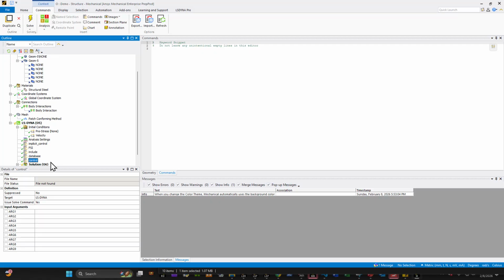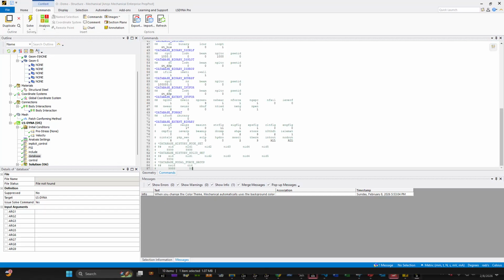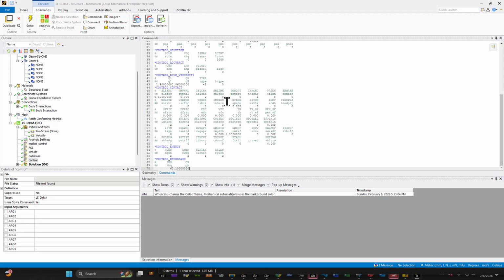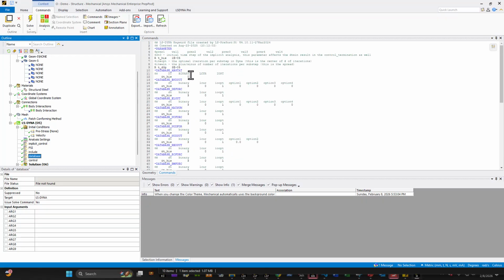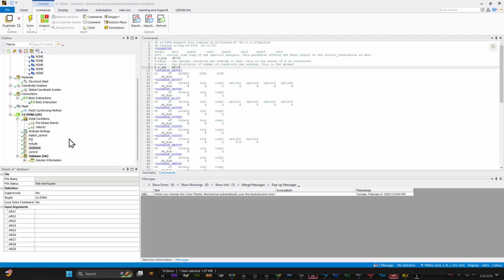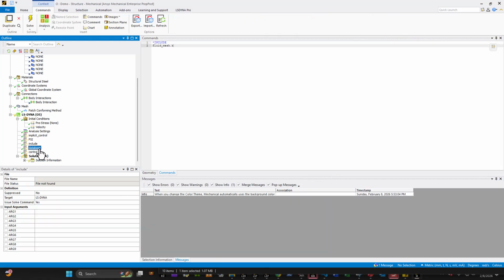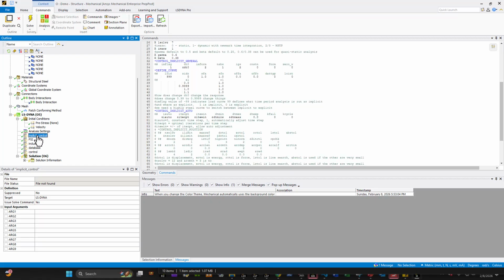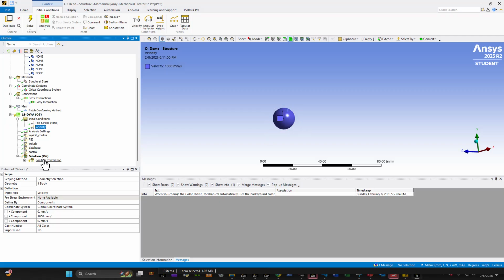If you've watched my video, you know I have these standardized database cards that I use for all my problems, and I have standardized control cards which I use for all my problems. I modify them on an as-needed basis, but this basically handles my problem really well. And in this case, I want to make sure my ID is actually pretty small, which is good. Okay, that's all I have to do, right? All I did was add a control card, a database card, an include file, then define my FSI, then define my implicit control. And with that, this ball basically just dropped through air at 1 meter per second, right?